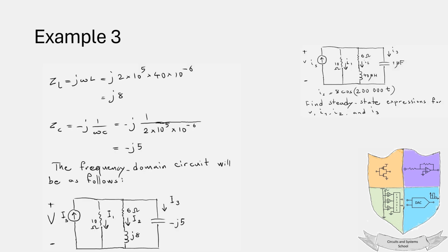If the 3 impedances are replaced by an equivalent impedance, the voltage across the impedances can be obtained by multiplying the phasor representation of the current source by the equivalent impedance. After that, the current in each branch can be obtained by dividing the obtained voltage phasor by the impedance at that branch.